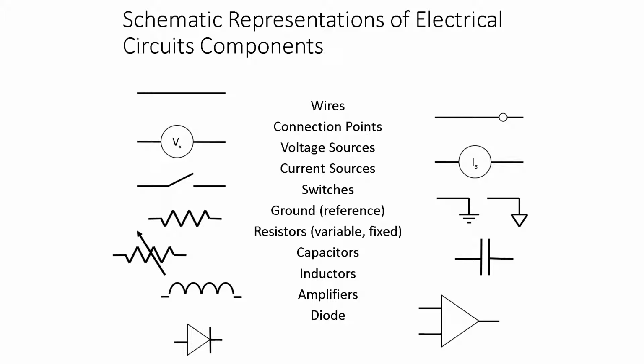There's something you do in circuit boards called conformal coating. It's like a thin plastic resin, kind of an epoxy, that you coat on top of them. That locks everything down into place, and makes sure that if water gets in there, it doesn't touch the circuit and short it, or dust, or something like tin whiskers if you're doing satellites. Tin has this property that it makes little whiskers that come out, and that can short things. So we usually cover over that with something like conformal coating, just to make sure that nothing can get in there and give us a short circuit.